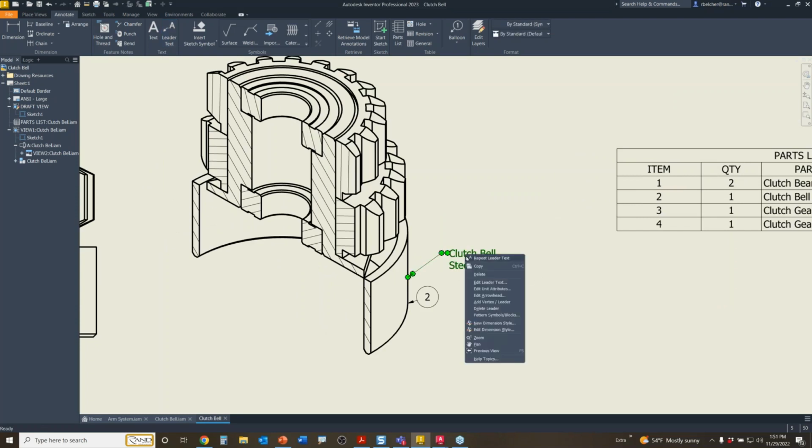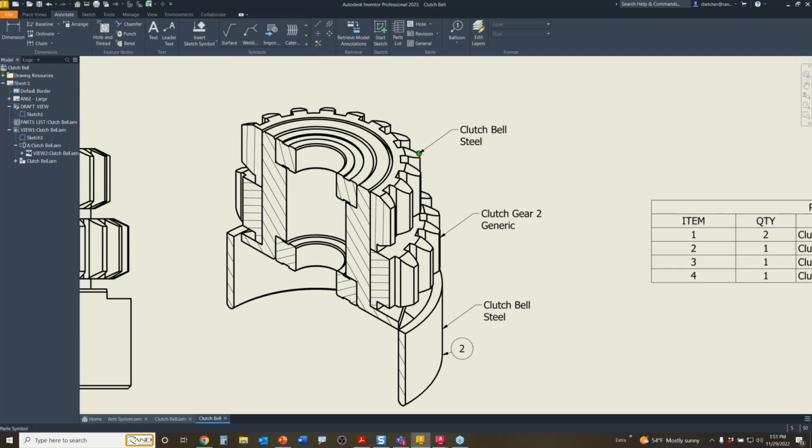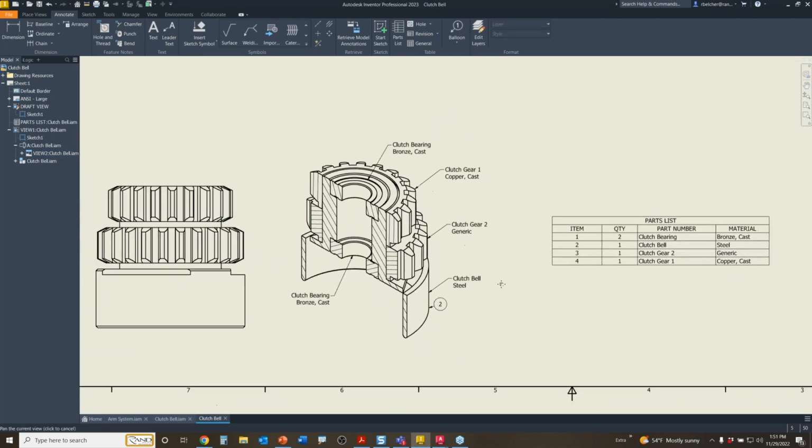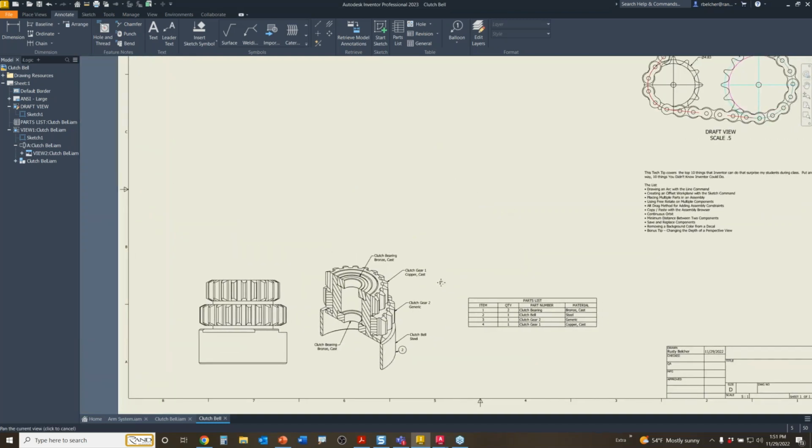Nice. Well, watch this. Right click, copy this. You have to do it this way. You have to right click on it, use copy, and then right click and select paste so that it comes in on the cursor. But watch, I can then drop that there. Drop that there. Drop this one up here. And drop this one there. These update based upon what you're hooking them to. There we go. That leader command, that trick is amazing, and it works in so many different ways. It is really, really nice.